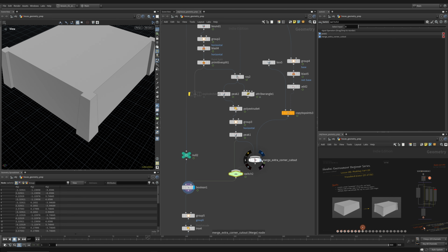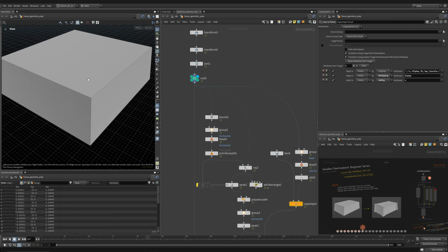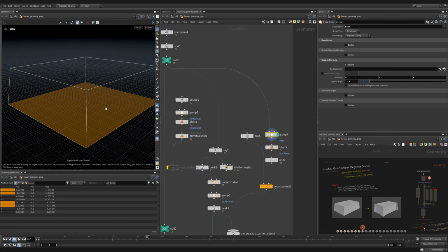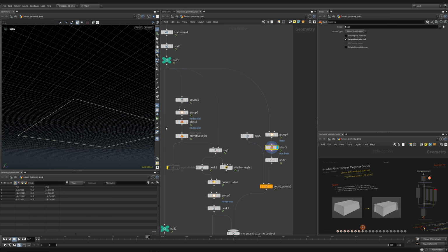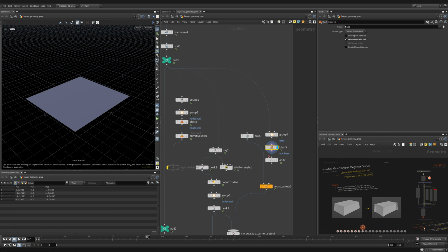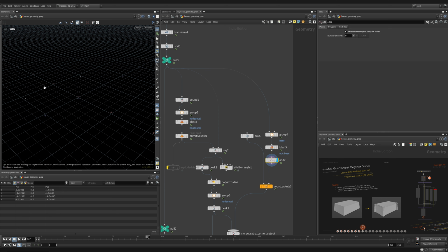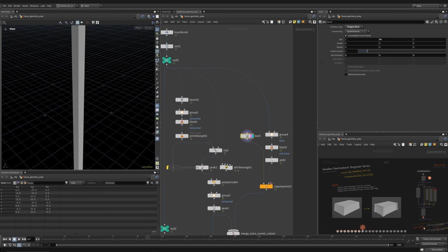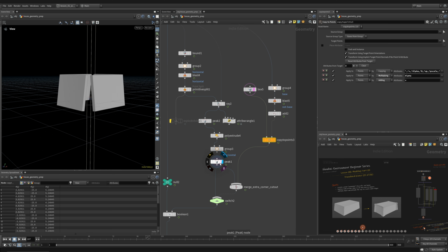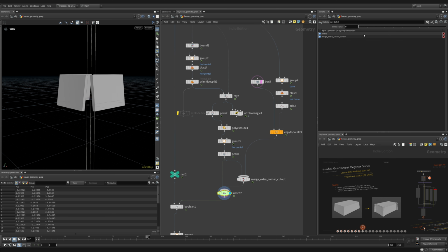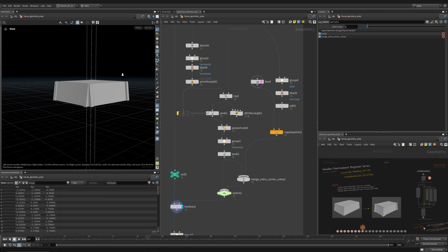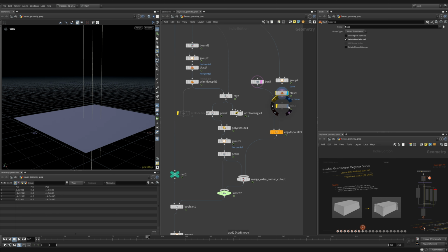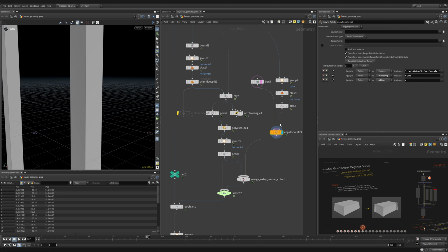And the way I made these extra tall points here was I got our object, this input shape. I grouped by normal, so I picked only the bottom, the base of these, removed everything else with a blast, so space G to frame. Add, I actually want to keep just these points. And then I want to copy this really tall box here, which I've set with the box. I want to copy it to those points, merge it with this shape we created, and then Boolean, so I'll switch it to 1, with this shape here. And then this add I actually don't need. It looks like it is having me need it.